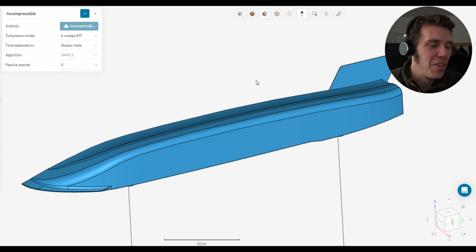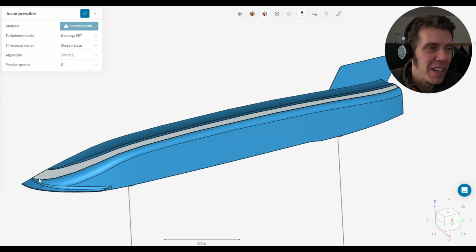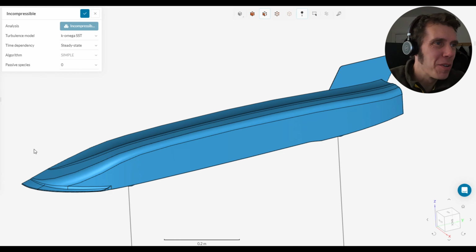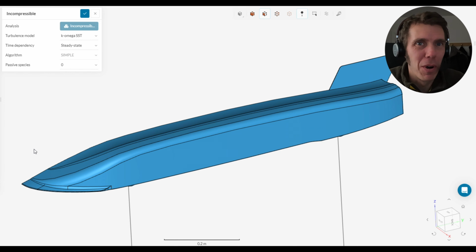Let's talk about splitters. You might be wondering why I haven't mentioned these protrusions from the front of the car that are quite common in RC speed running, and that's because I tried them on my first speed car, the Cone Mark 1, and I had to take it off pretty much straight away because it was scraping on the ground, causing extra drag, and it was catching on some imperfections on the runway surface and nearly causing the car to flip over.